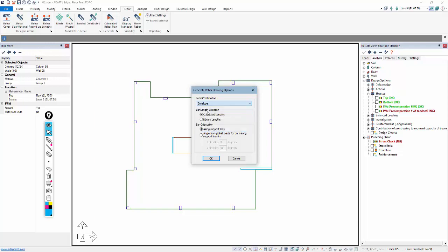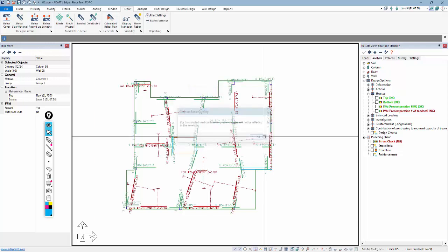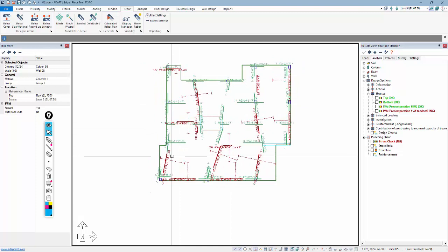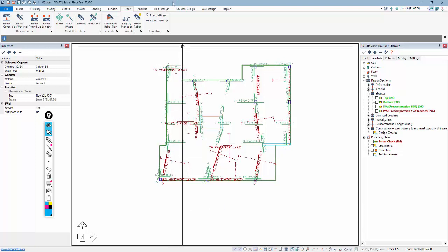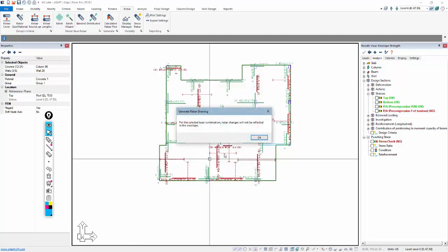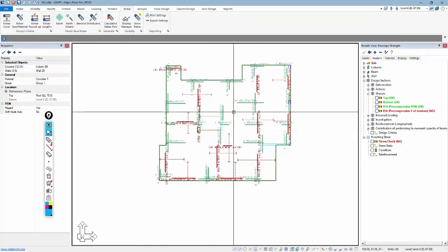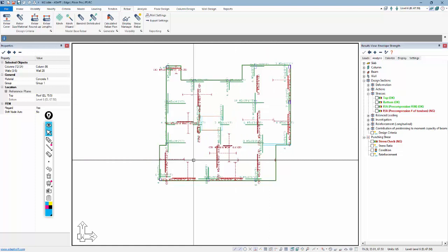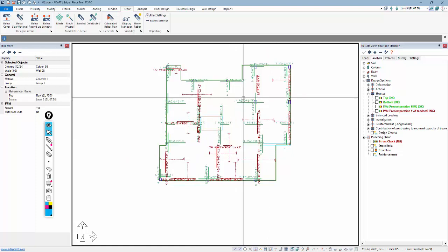And if I calculate this for service and execute that, this is the rebar that's needed to meet minimum requirements per code. So you can see all the rebar aligns with the support lines. It's parallel to the support lines. If I come back and generate that rebar through use of the same dialog, however, in this case, I'm going to align it relative to these axes. Now you can see everything's aligned, and we do a conversion for the quantity of reinforcement in the slab.